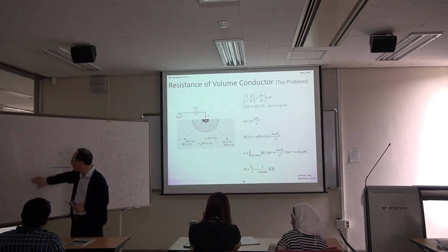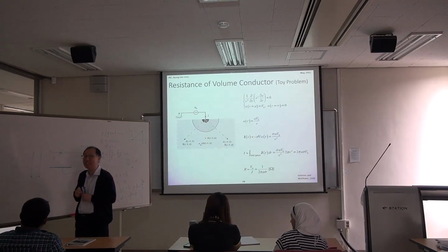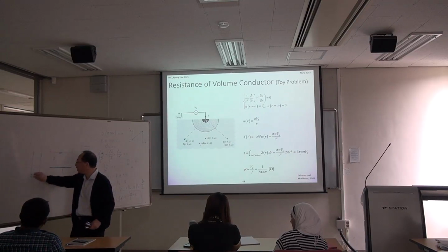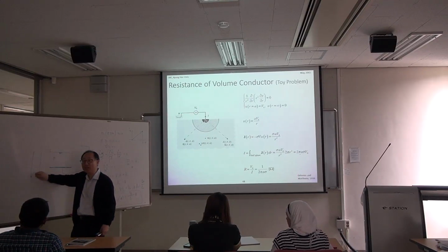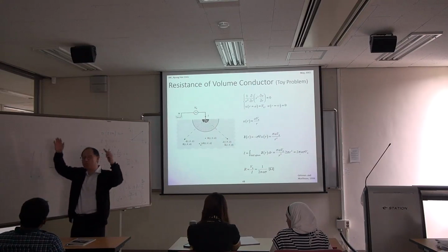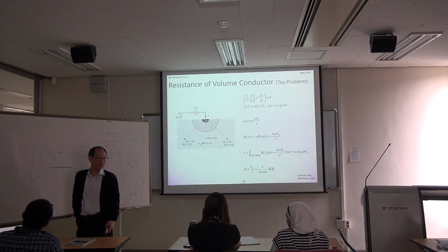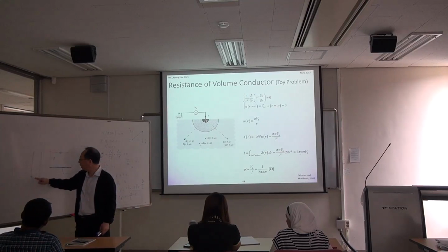No. You are measuring the impedance of the tissue right here and here, okay? You are not seeing anything in the middle, because the current density around this area is much, much higher than the current density around this area. So this impedance measurement has very small sensitivity to the tissue down here.